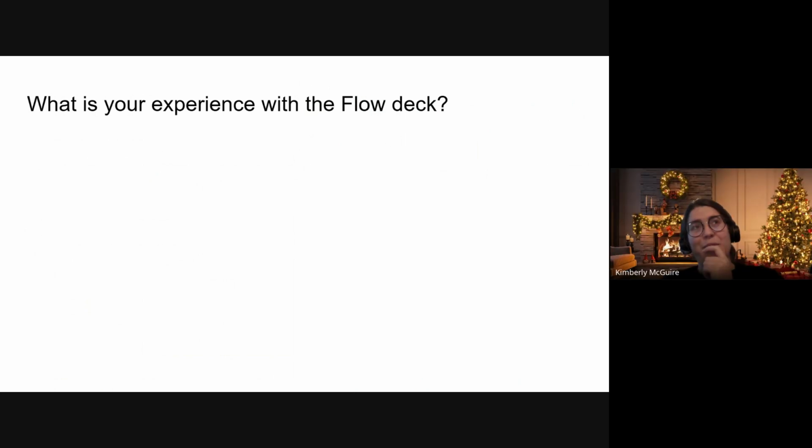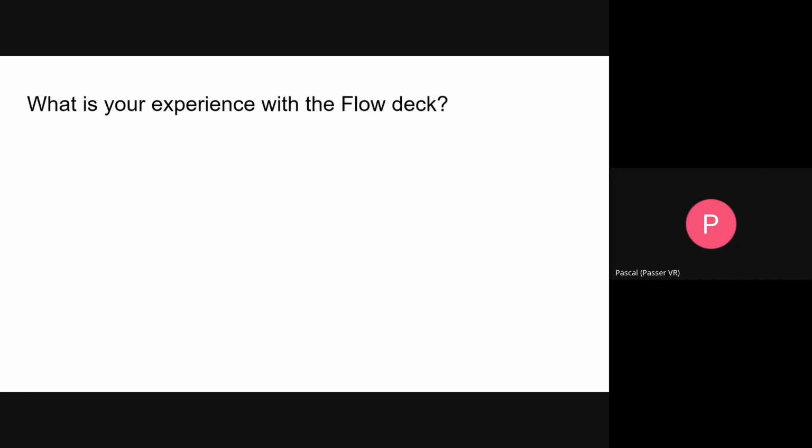What pops into mind is that you saw before, for instance, the low texture, the gray video, that when it was closer to the ground, it was able to detect something. So I would say perhaps in your state machine, maybe it should go a bit lower so it is able to detect more texture again. Like with an airplane, the further up you go, the less you see.